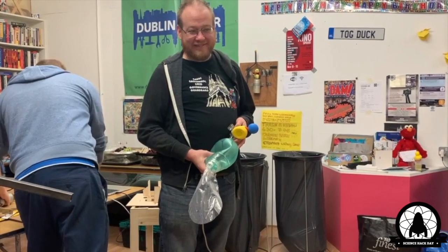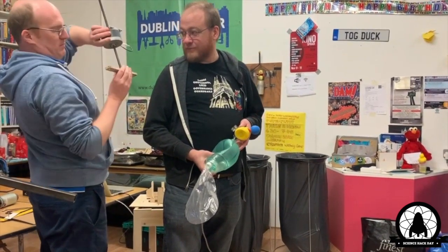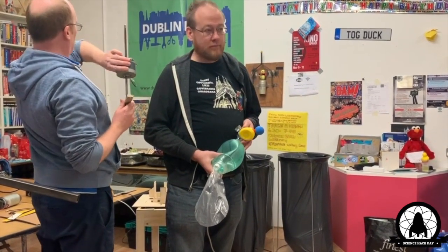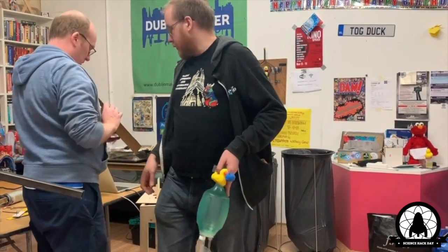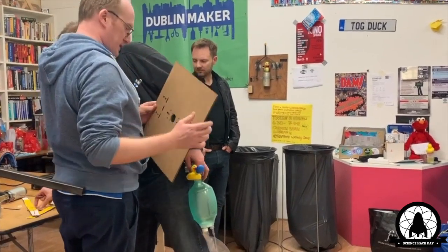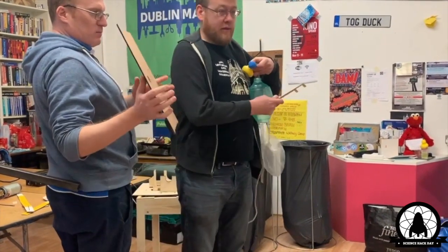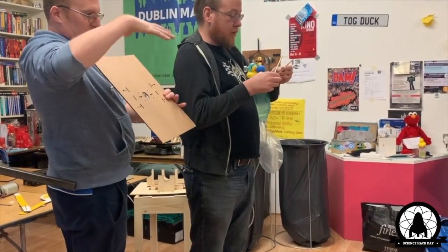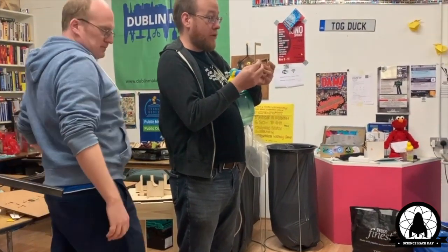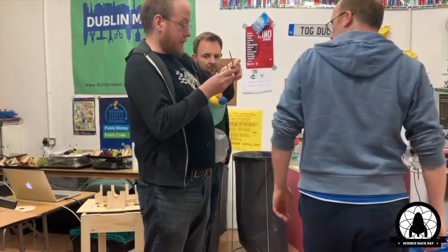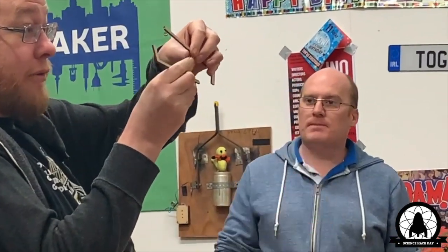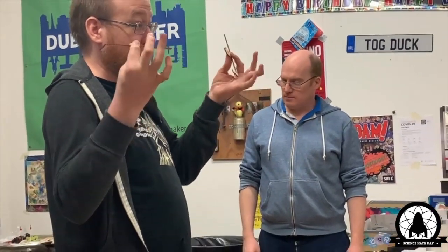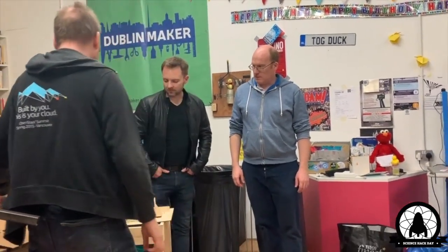Then we tried some other ideas, but again we ran into torque problems. But eventually we came across one that actually worked: the rack and pinion system. We tried some setups for the laser cutting. So just a simple laser cut gear, some laser cut racks, spin the gear, it opens and closes. The basic mechanism works. We cut it with as small a piece of wood as we could to try it. You can't make that in cardboard.